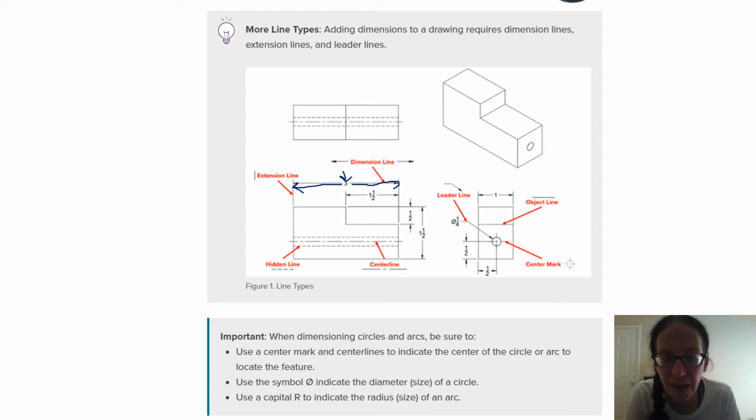And so we see a dimension line there. Now there's some other lines there. We have here, I want to keep using the blue, what's called an extension line. So we don't write the dimensions on the figure itself. If you look closely at these, none of the dimensions are written on the actual figure. They're all written outside the figure. We don't want to clutter up our drawings by writing numbers and having these lines. But you can't write all the measurements on top of each other.